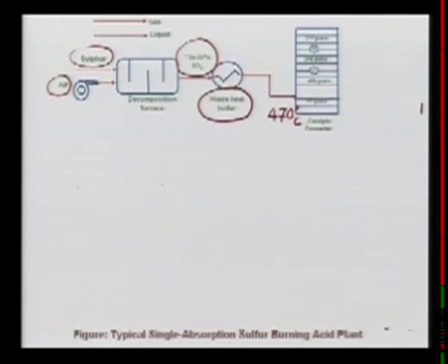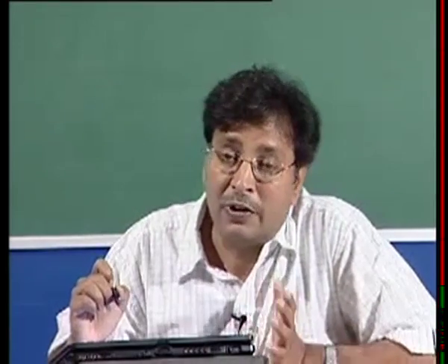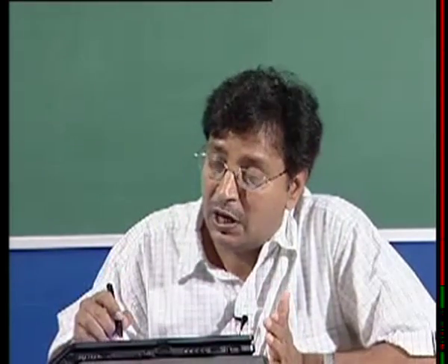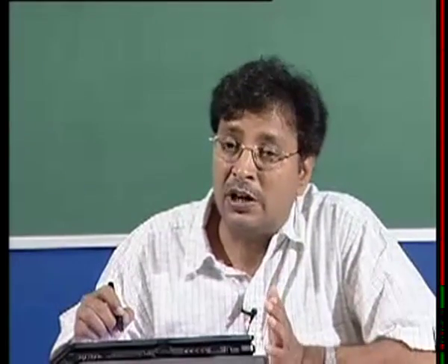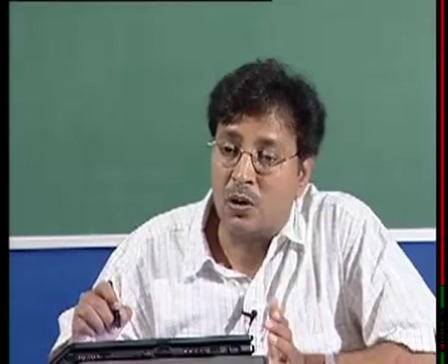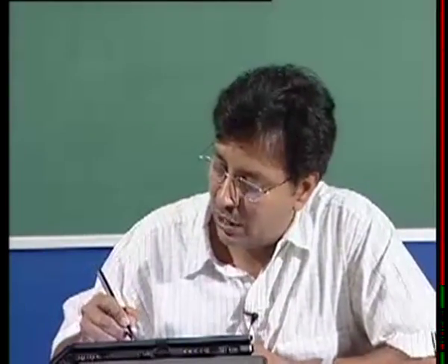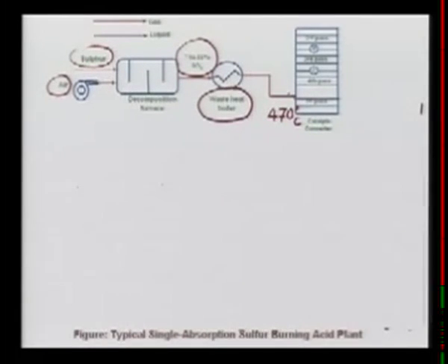The idea is, why do we need to do it in phases? The phases are very important, because we have to make sure that the reaction is going continuously in the forward direction. So we must continue to recover the heat, else what will happen, if the heat is more, the reaction will go more towards the backward side, and SO3 will go back to SO2, and we will not get the SO3. So let's go back to the flow sheet.